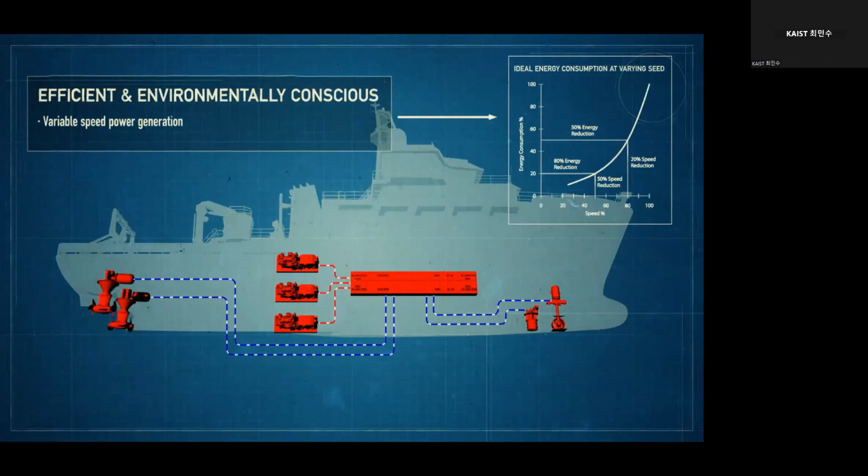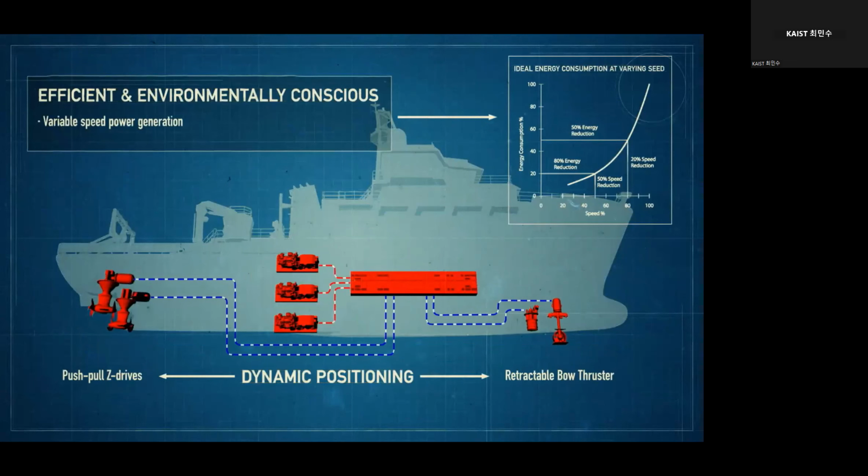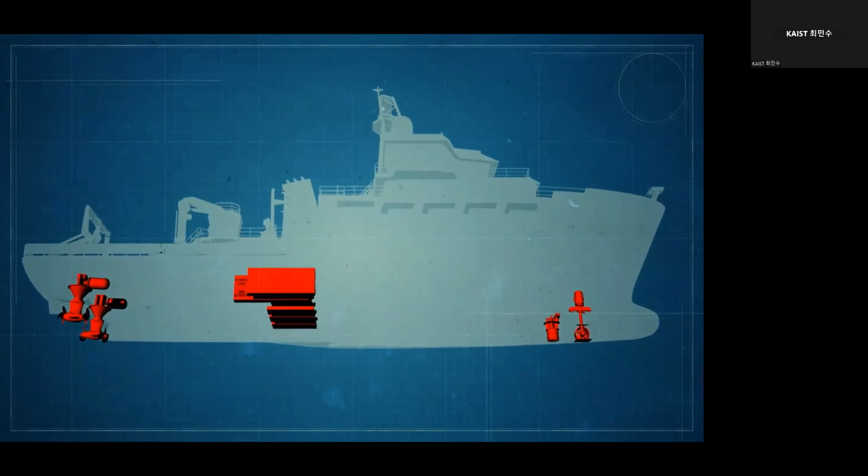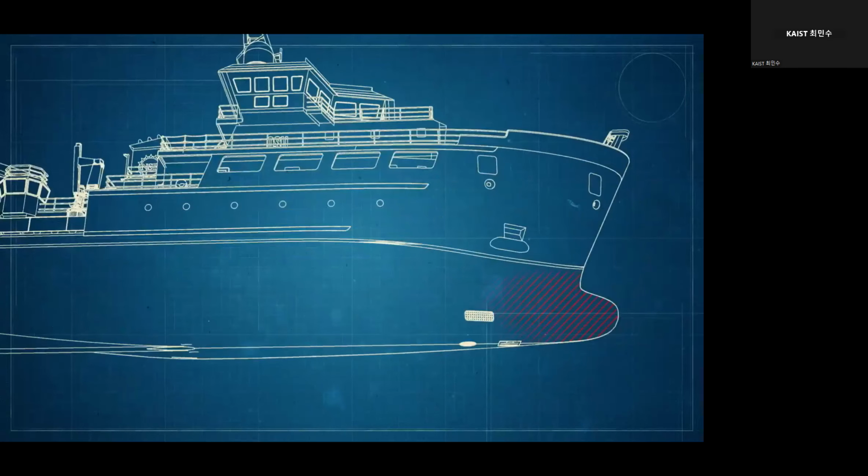When we were approached by Oregon State, one of their key objectives was to make this as green a ship as possible. We've gone to great lengths to incorporate the latest technologies into the ship to keep it as environmentally friendly as we can. We've decided to use variable speed alternators to make electricity. We've also used LED lighting wherever possible. We're using waste heat, the heat from the engines, to heat domestic water and to make potable water for the ship.